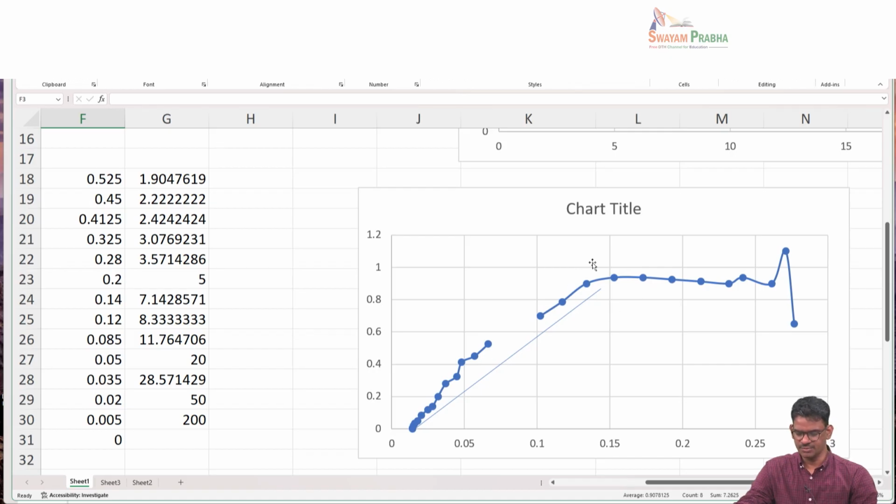And here we are making an assumption that this falling rate period is not sensitive to the change in air velocity. We are going to assume that changing the air velocity only changes the constant drying period, not the falling rate period. How do we justify that? Between the test sample and the original sample, I am changing the air velocity. When I change this, I am only scaling the constant drying rate. I am not changing the equilibrium moisture content, the slope, the critical moisture content, nothing with regard to the falling rate. How do we justify this assumption?